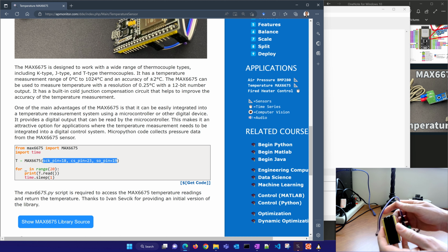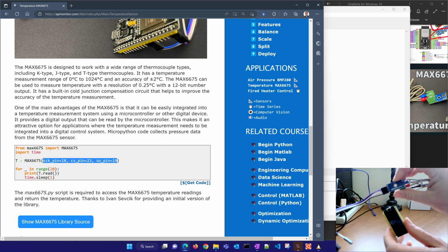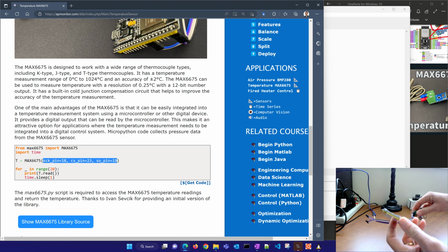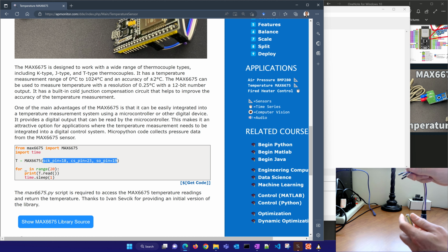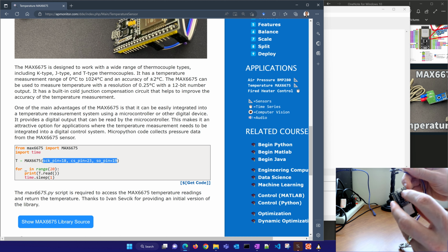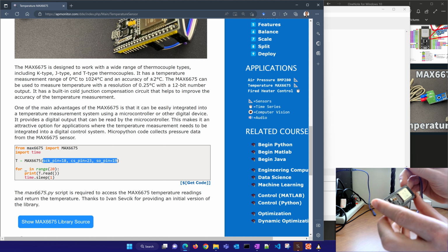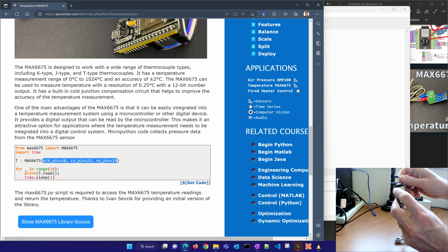I'll go ahead and unplug it, and then I have these pins already hooked up on this side, and I'll plug in the white and the black. Those are going to be my power, and they're connected here to the VCC and the ground. The very first thing I need to do is look at these very small characters here, and there is 3.3 volts right here.